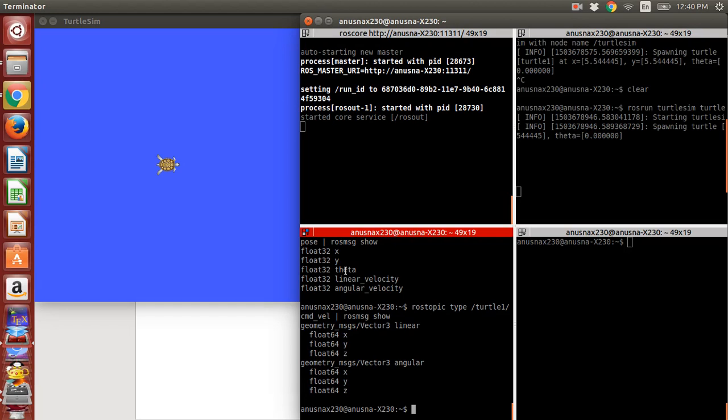Now linear is the linear velocities, it is UVW. For linear velocities, all that we are worried about right now is just the float 64 x, because this is a 2D vehicle, so we are not considering what will happen to the vehicle in its z-axis. We also have to consider the turn rate of the vehicle, because that is how the vehicle aligns itself and moves towards the waypoint, something that you will be doing.